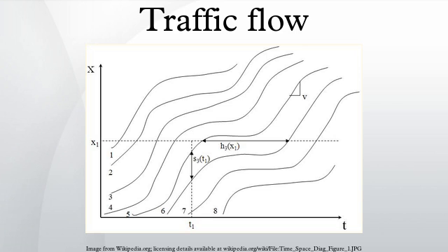State U, with flow rate Q, corresponds to the queuing upstream of the truck. On the fundamental diagram, vehicle speed V is slower than Vf. But once drivers have navigated around the truck, they can again speed up and transition to downstream state D. While this state travels at free flow, the vehicle density is less because fewer vehicles get around the bottleneck.